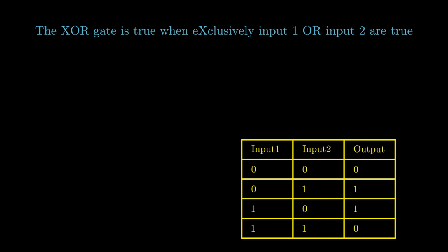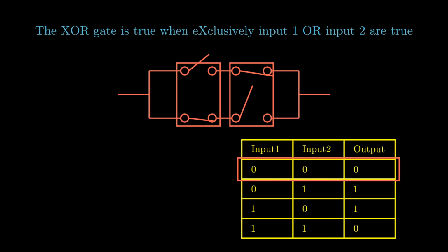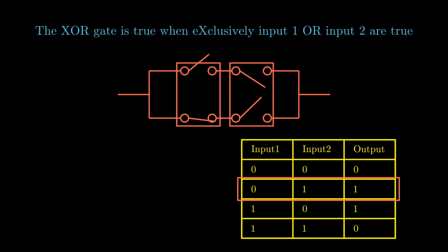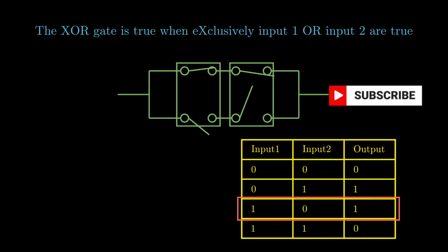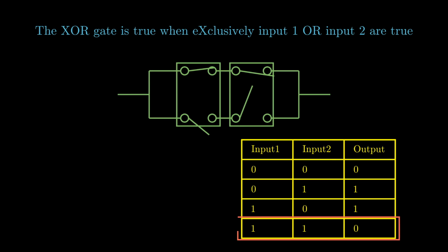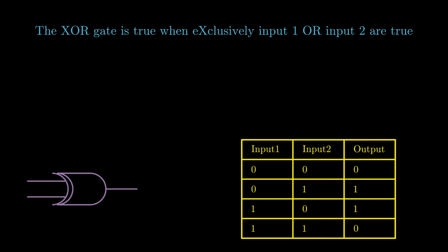Note that in this circuit, we are assuming that if a switch is drawn upside down, it just takes the opposite state of whatever is being input. Again, this is only drawn this way to illustrate my point. You won't encounter an XOR gate drawn this way out in the wild. Let's try all of our combinations and see if our truth table is accurate. As you can see, turning one input on will result in a high output, but turning them both on results in a low output.